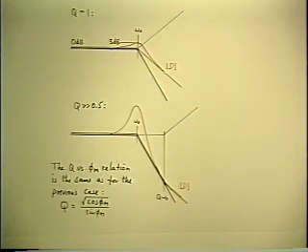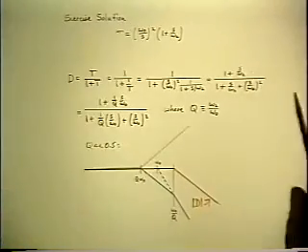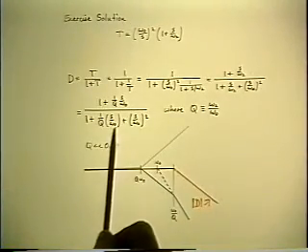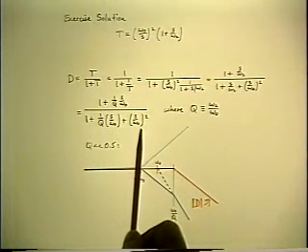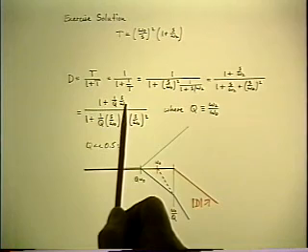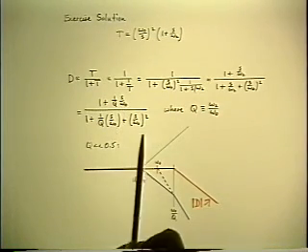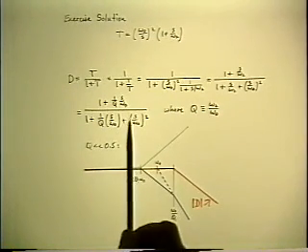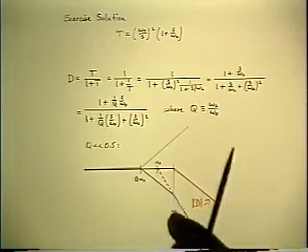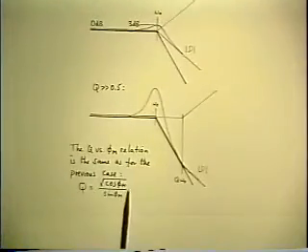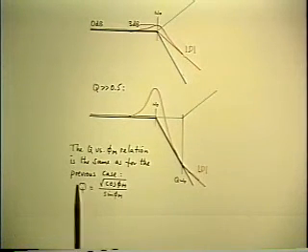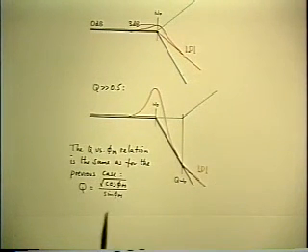Now, I was quite surprised about that when I derived it, because the formula for the D is significantly different for this case. It's got the quadratic in the denominator, but it has a 0 in the numerator as well, which the previous result did not have. It had only the quadratic. So I fully expected, when I first worked this out, that I would get a different result for the relation between phase margin and Q. So I was surprised when it came out the same.